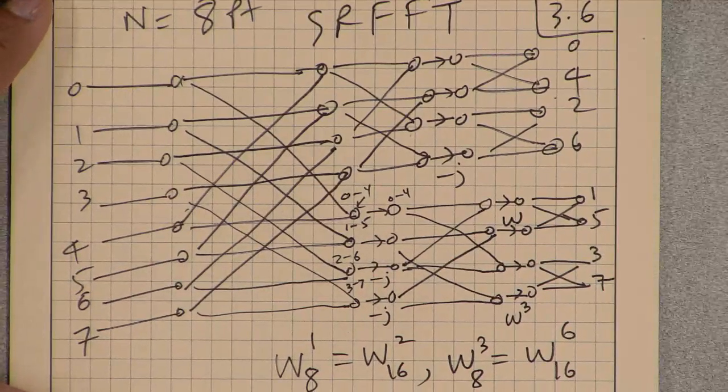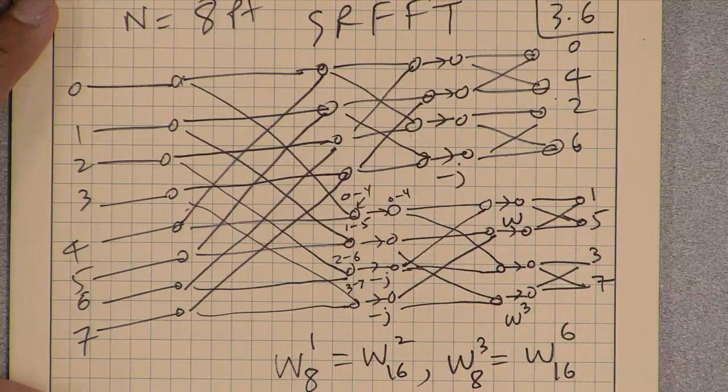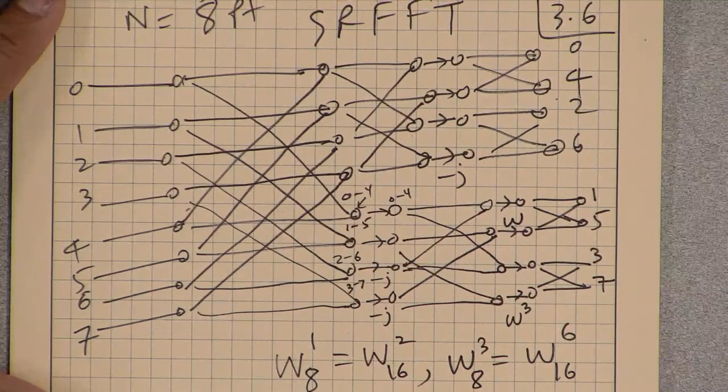It has n log n complexity, but the split radix FFT reduces the number of multiplications some more. You can look at the tables to see how much it reduces. Not that much, but it does reduce to a great extent for a very large n. So there has been interest in these kinds of things.